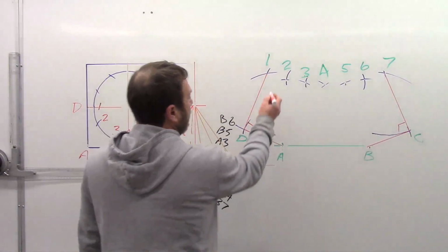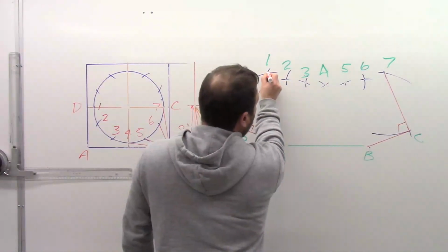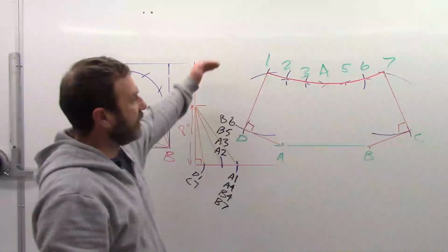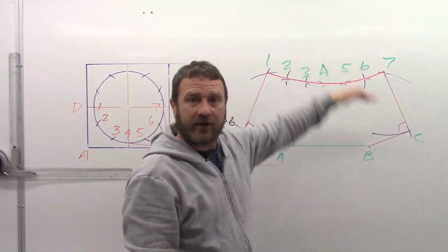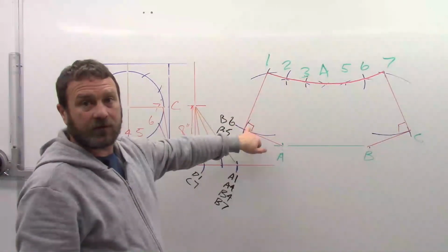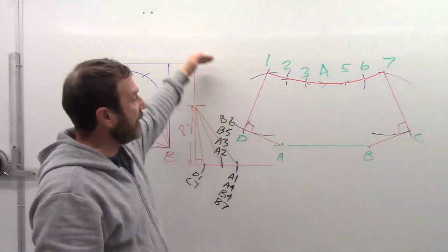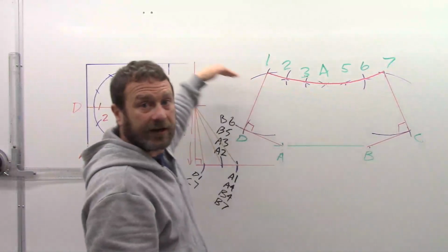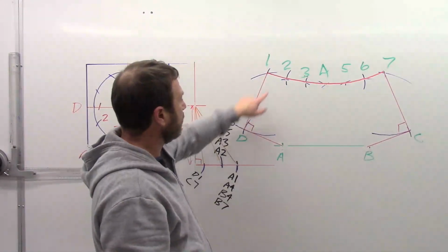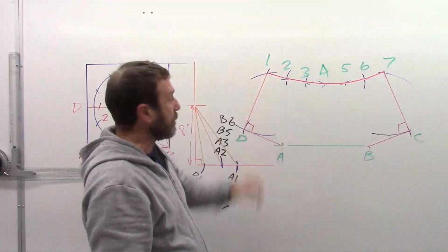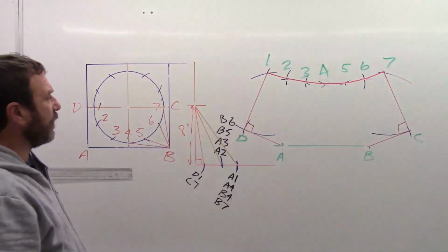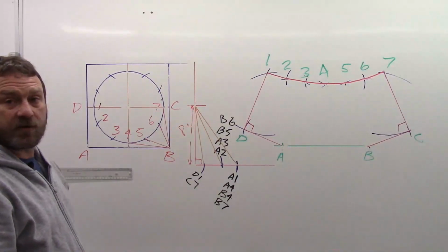Okay, but now you're going to use a flexible curve and draw in our arc here. Okay, that should be nice and smooth. If you see kind of a lump or bump in it, again, something's wrong there. And that probably will transfer to out of 90 here, but you never know. But this should be a nice, smooth, clean arc there. Okay, so check for 90s always. Check for a smooth arc. And that's our half pattern. We'll have to cut this and flip it and make another one. Half pattern for a squared around triangulated.